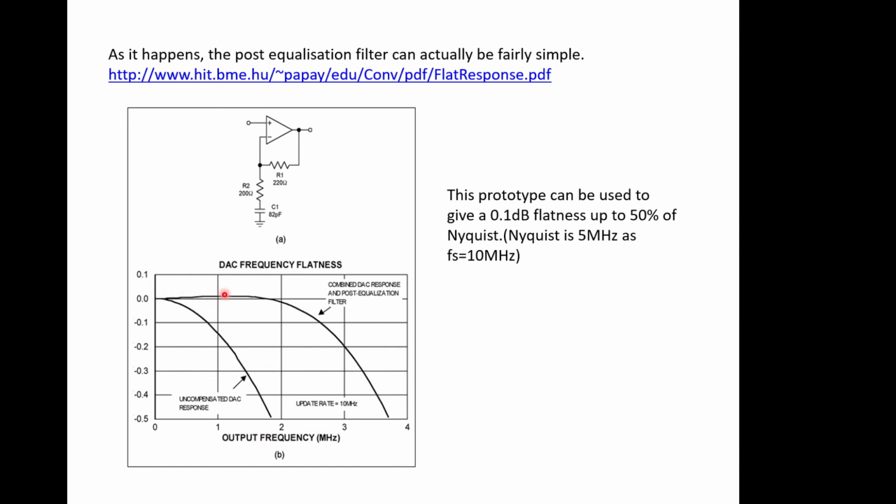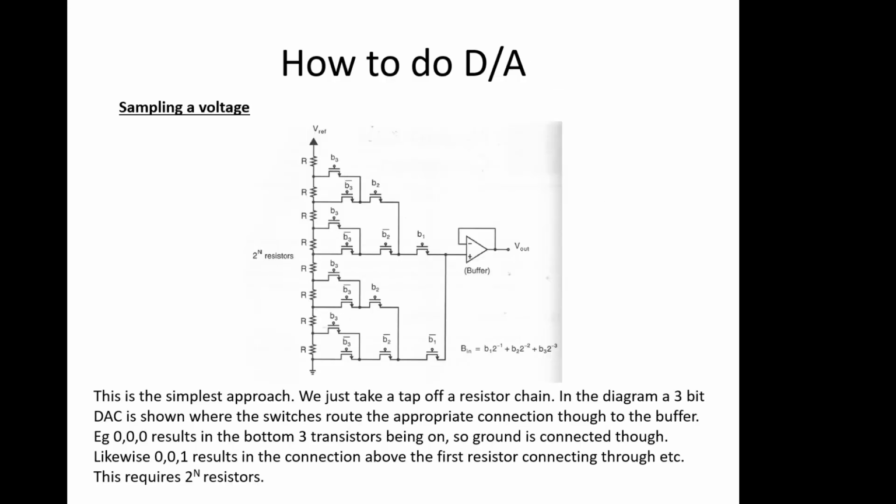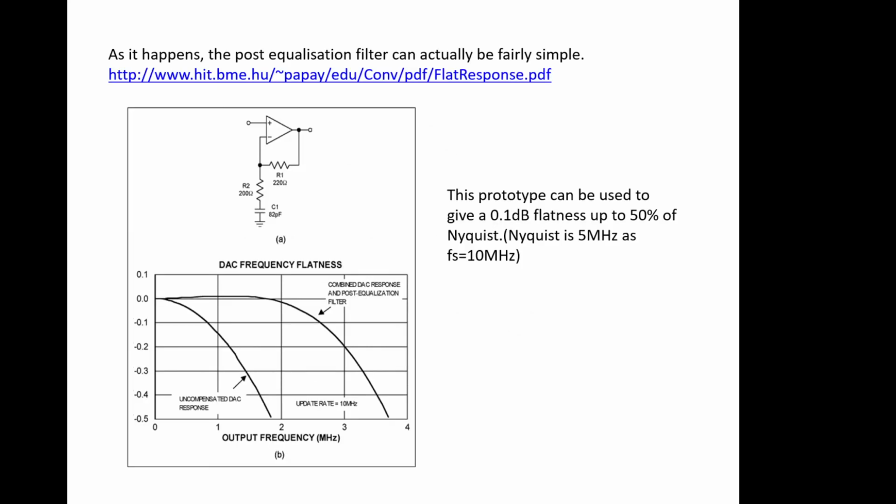So be aware of the frequency response of sample and hold systems. It doesn't apply to sample and holds on the inputs of digital systems. It's only if you're bringing signals out into the analog world that this frequency response actually applies.